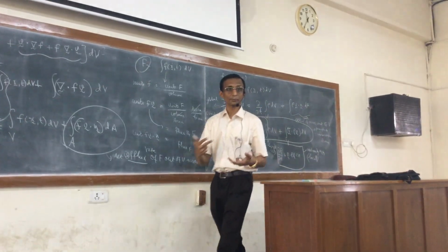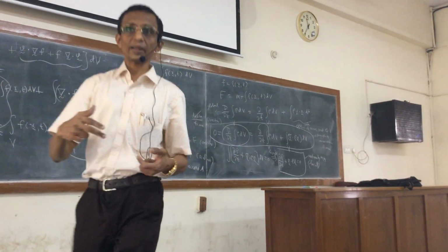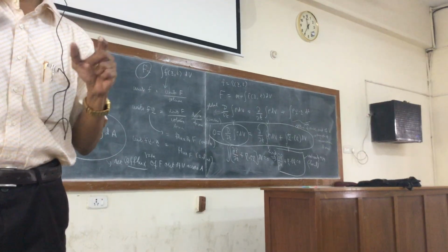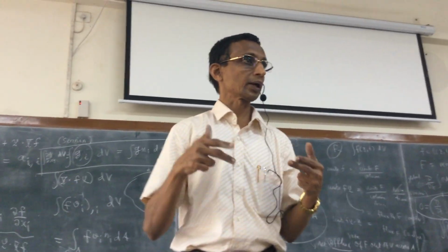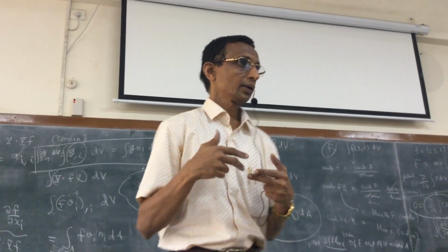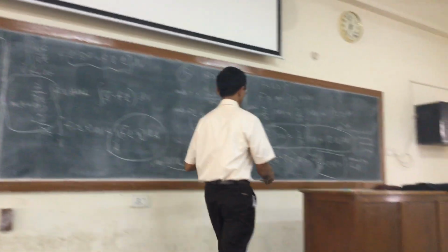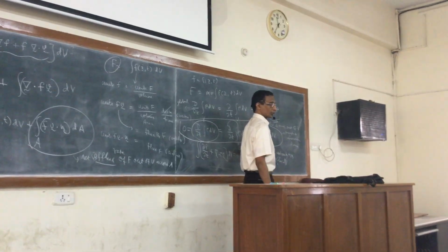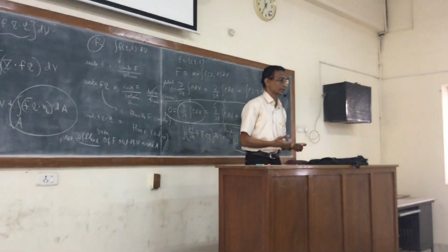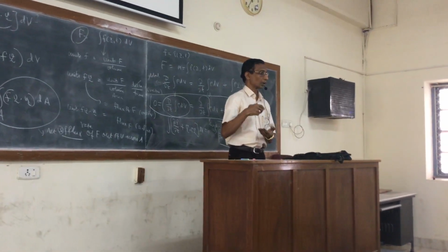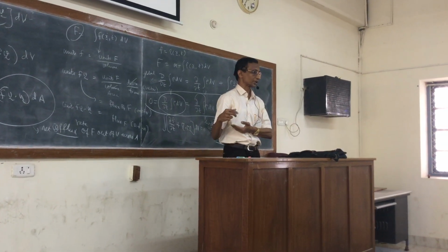The property of a body is that its mass is conserved. So from that we are collapsing to a point within the body and then concluding that the quantity dρ by dt plus the divergence of ρ times v is valid at all points within the fluid. This is a standard procedure: from a global balance we get to a local equation.